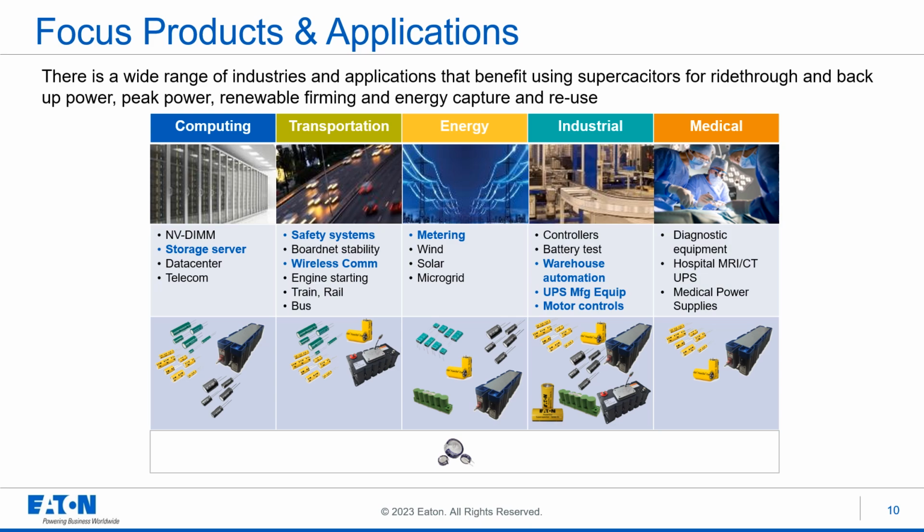Supercapacitors play across a broad range of industries and in several different applications within these industries. I have omitted consumer applications on this chart. Coin cell formats play across all industries for real-time clock backup. Then you can see here there are both cylindrical, board-mounted cells and larger modules for various applications. In computing, the dominant application has been backup power for memory cache. More companies are starting to look at supercaps for backup power for data centers and telecom base stations as well.